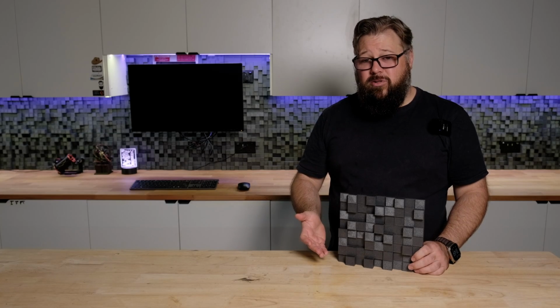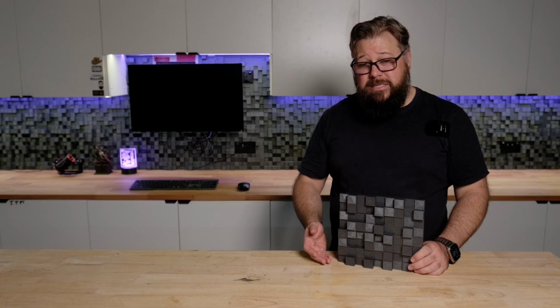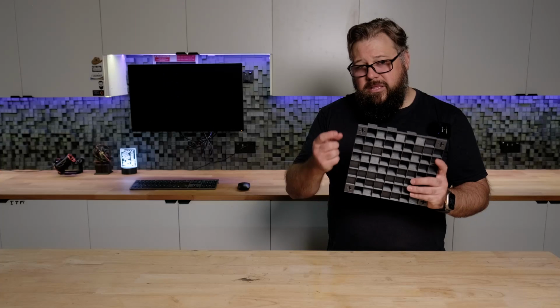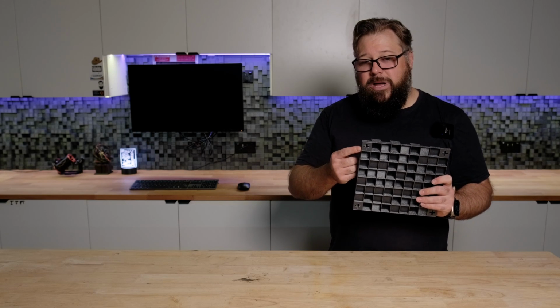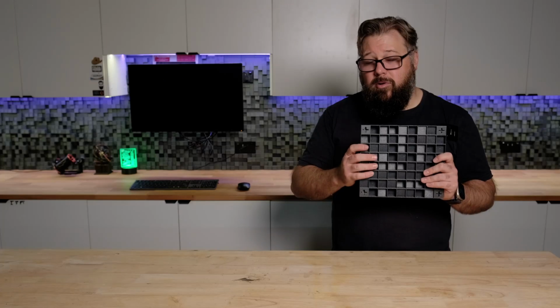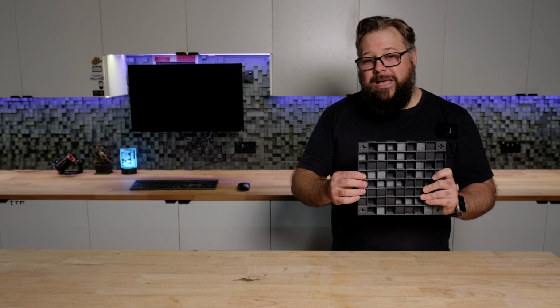If you haven't had a good look at them, let's talk about the actual panels. This particular panel is an 8x9 well QRD with a depth of 5 through 30 millimeters. The base includes 2 mounting options. One is adhesive, but it's also been designed so that you can use a small drywall or similar screw and just slot the panel into position.